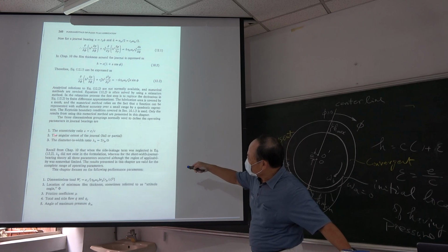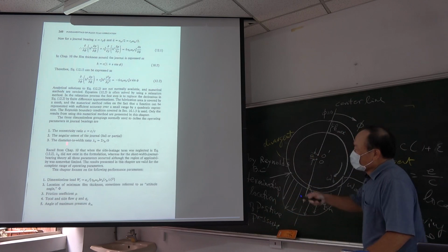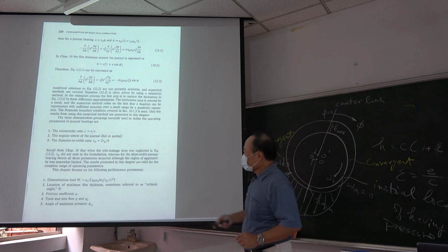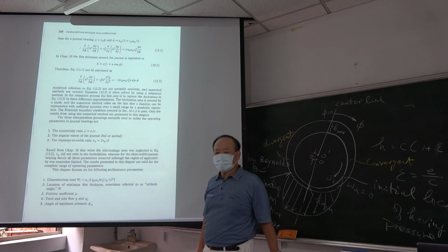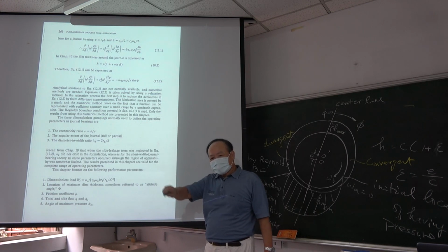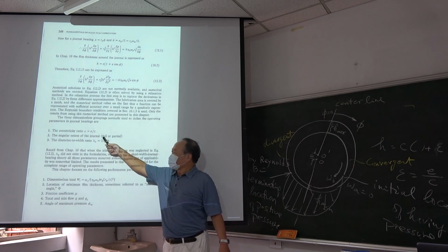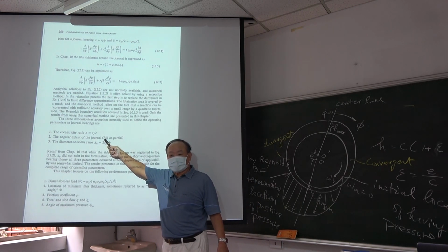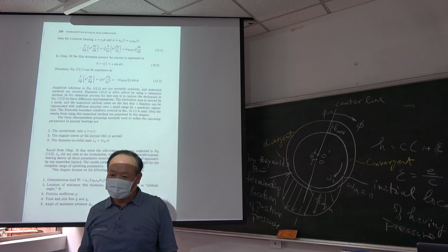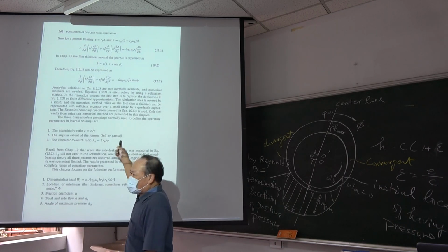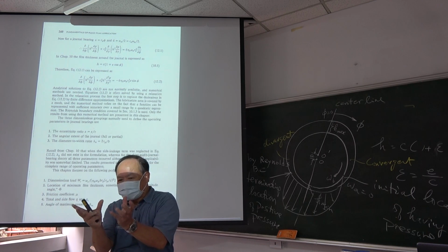The second is the angular extent of the journal bearing. Your bearing may be full or partial. In the full journal bearing, the motion is very precise, in high precision. If you want your motion to be very accurate, you use the full journal bearing. Of course, this kind of journal bearing has a high cost.